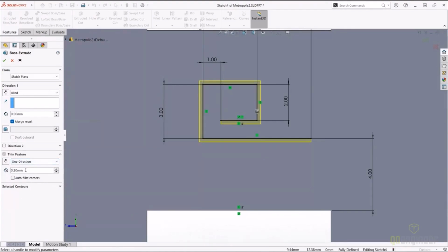And I can add my material thickness to the outside of the sketch, the inside of the sketch. Maybe the dimensions that I knew were at the middle, right? The center line or the midplane. Or maybe I knew a certain amount of information in each direction from where the sketch is.